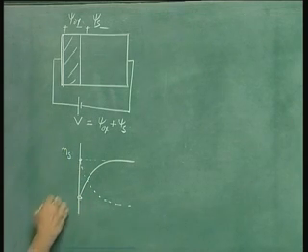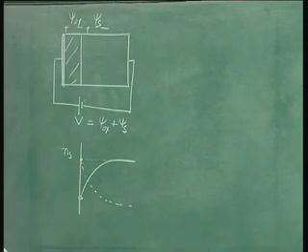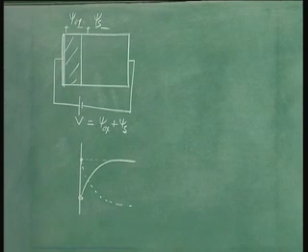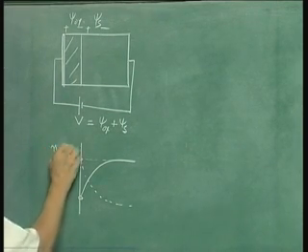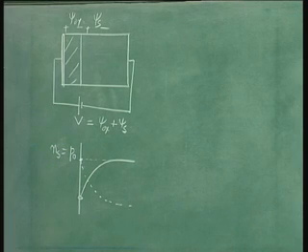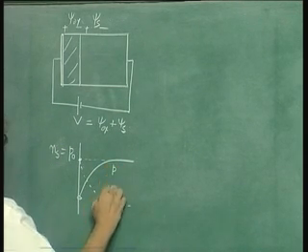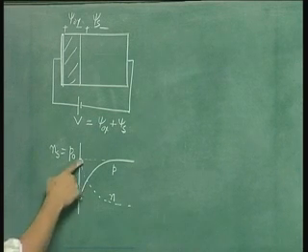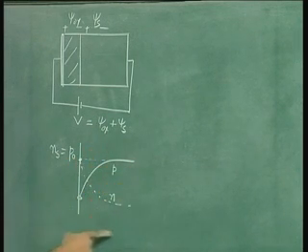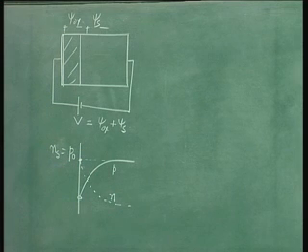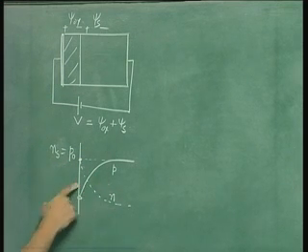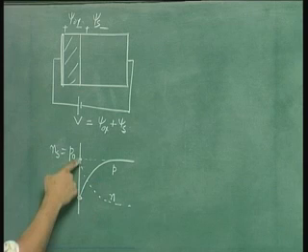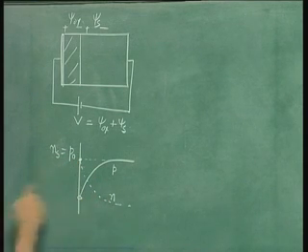So Ns is equal to P naught. That is a point here. This is hole concentration and this is electron concentration at threshold. You can use the Boltzmann relation because this semiconductor is under equilibrium. So the Boltzmann relation gives you the potential drop in this region if there is a variation as shown here.